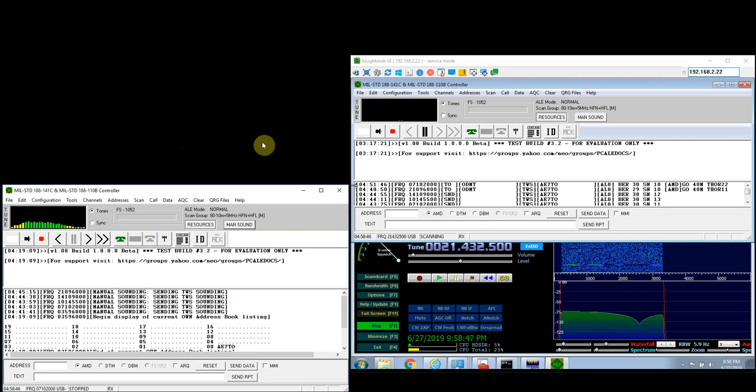I think that pretty well summarizes the idea here. Again, the bottom line is you're trying to figure out how to coordinate band selections, and for that matter make band selections on point-to-point HF links. And in this case, we're using PC ALE software to scan at all of the stations, and also the same software to transmit soundings manually from each station. And once net control sees what bands work by scanning the successful soundings, they can send out a message to everybody on the net announcing the desired band.